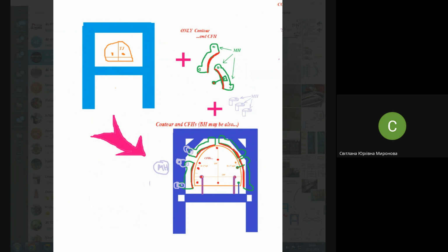How? It may be a set of locators, for instance, or for the very first time it may be just some pieces of thick wooden bars you bring and insert between the carcass of the jig and the template, filling the gaps with them, and clamping the template to the frame, to the skeleton of the jig, in this very first position for the first few minutes. Next, you mount onto the template.